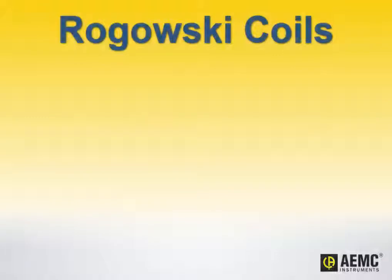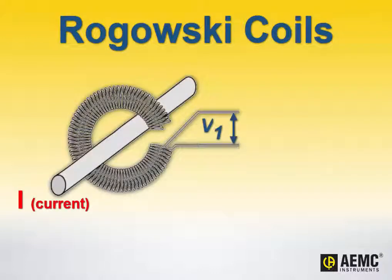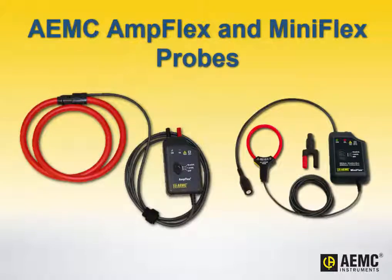A Rogowski coil is a device for measuring AC electrical current. The coil is a helical winding of wire, resembling a large spring, with one end of the wire passed back through the center of the coil. When the coil is wrapped around a conductor through which current is flowing, voltage directly proportional to the current is induced in the coil. The AEMC, AmpFlex, and MiniFlex families of AC current probes incorporate Rogowski coils.